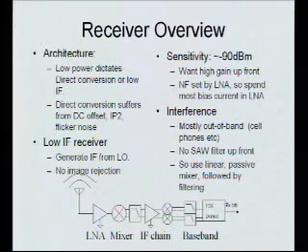I can justify that for essentially 2 reasons. There's 2 reasons you want image rejection. One of them is to not be interfered with by image signals. That's a really good reason. One way you can help reduce that problem is you make your IF programmable, so you can step your IF away from an image. You might lose one packet of data because you wake up and there's something sitting in your image. But the next time you wake up, you move it, and you put your image somewhere else. And in the ISM bands, it's actually fairly sparse at the 900 band, so you can usually find an empty channel. The second problem, which is more severe or less avoidable, is the 3 dB noise figure hit.